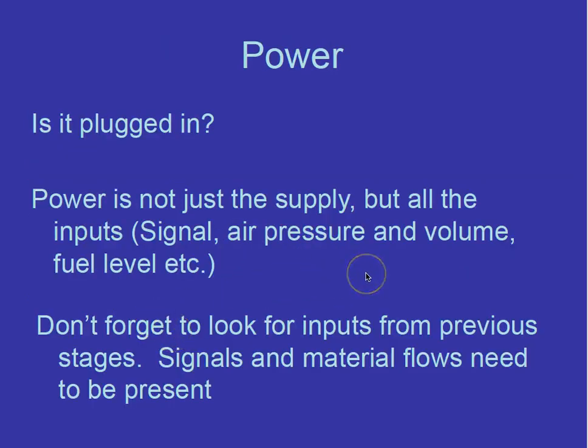Now power, is it plugged in? Power is not just the supply but all the inputs: signal, air pressure and volume, fuel level, etc. So all these are included in your power. So you need to see if your power is on or off, and before you touch the circuit, you should first have all the tools, and then you should first turn off the power and see if everything looks okay or not, and then try to understand the circuit, what is happening there.